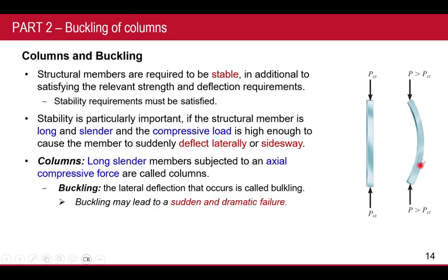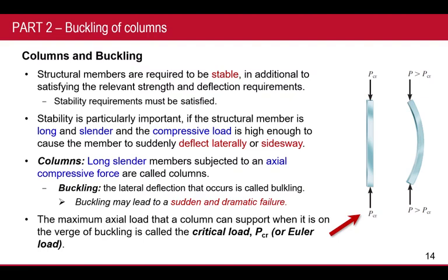This means it is not straight enough. If you put a bend in it, the structure is not stable. So here you must consider whether it stays straight or bends. Structural stability is one very important thing, so we should consider buckling. But remember, for buckling, when we put a load at the end, we come to some critical value.